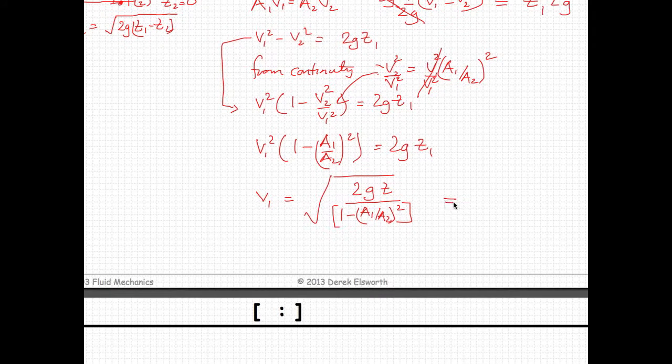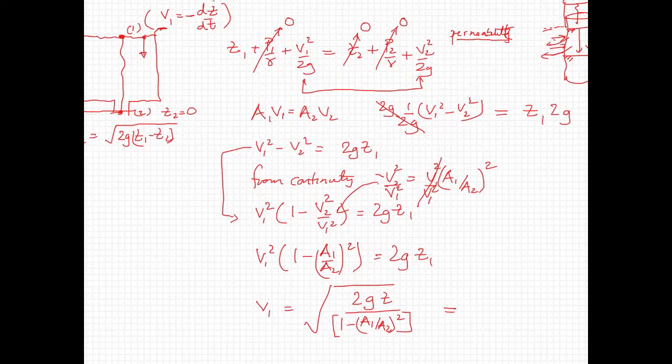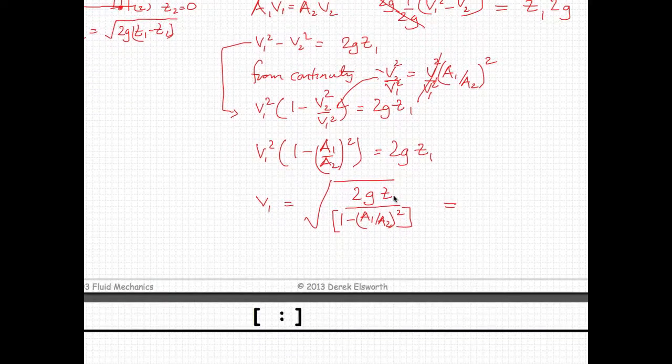And so what we want to do now is realize that the velocity of this upper surface is equal to this change in elevation with time. I purposely wrote this not in terms of z1, but just as z, so whatever the elevation is at this upper surface, which is what it was in our case before. We can attempt to write this as the rate of change of the elevation of the surface with time. V1 is equal to minus dz/dt, because the surface is going down as time increases and velocity is positive. The only way we can make that the case, because of the sign convention for elevation, is to have that negative sign in there.